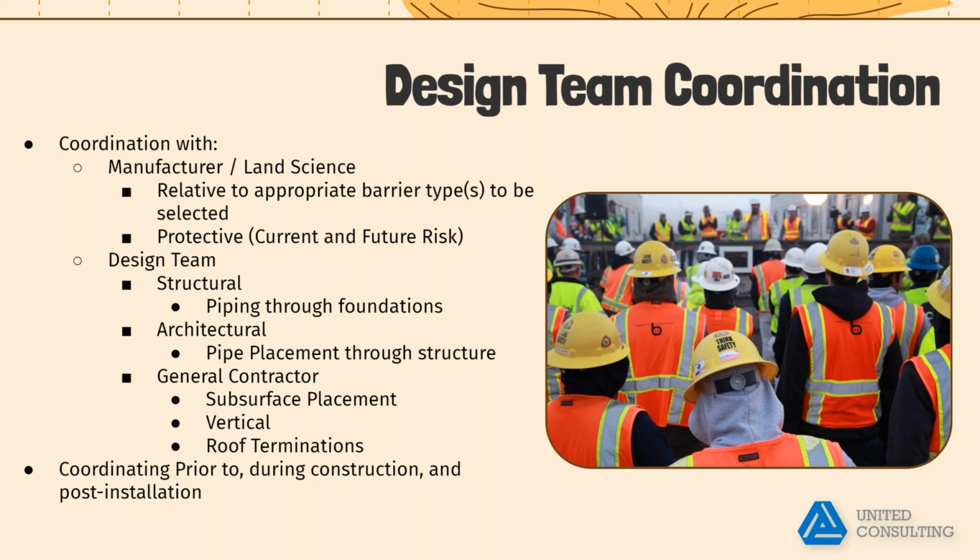through. Through the architectural team, does the vertical discharge pipes have a chase or a place to go without significant bends in the pipe? A lot of projects I've worked on, depending on the architect and design team, there are changes that occur between design and construction. So it's important that you have a great relationship with your architectural team to understand when they have a change that they take you into account during that change. As a rule of thumb, with each bend in a vertical pipe, you roughly see a 50% decrease in airflow. So it's very important for those chases or those pipes to have a home going straight up towards the roof.